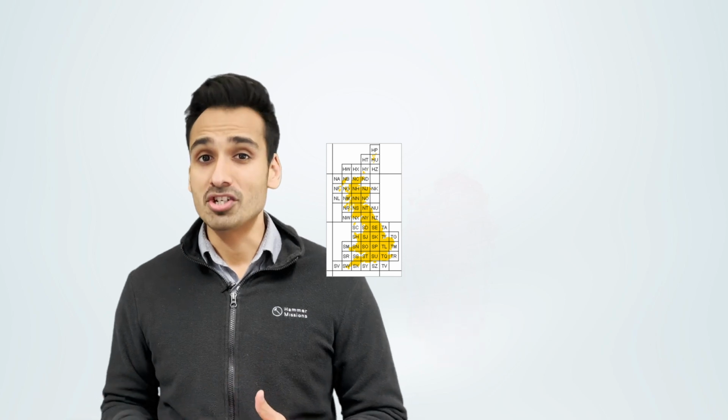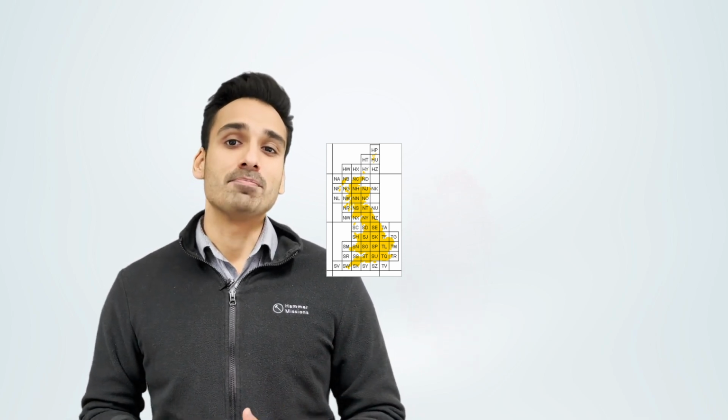The next one we've got is coordinate reference system. Coordinate reference system is basically, as the name implies, a system that is used to describe what coordinate system, what reference system, is being followed. Depending on the geography you're in, there might be lots of different coordinate systems, lots of different ways to describe the X, Y, Z positions of the drone, map, or model. And so what particular system is being used is referred to as the coordinate reference system. For example, in the UK, a coordinate reference system that is commonly used is the British National Grid. So that's just basically the reference system.